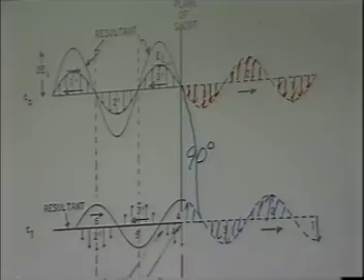Take this one here. Instead of going 30 to the right, it hit this short circuit, reflected out of phase, and it went over here. So instead of being over here, this signal is over here. Take this one, 90 plus 90, which is this number 3 line right here. But instead of being negative over here in this phase, when it hit the short circuit, it was reflected positive and traveled back here, so it is positive here.